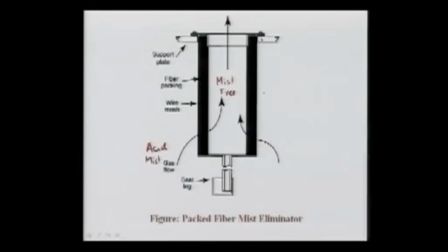Very quickly, it might be a good idea to give you a little feel about the SO2 emissions and the conversions. Suppose the SO2 to SO3 conversion is, let's say, 90, and here are the SO2 emissions, with a little arrow up there. If only 93% conversion is there, emission is around 48. This quantity is in terms of kg of SO2 per ton of acid.